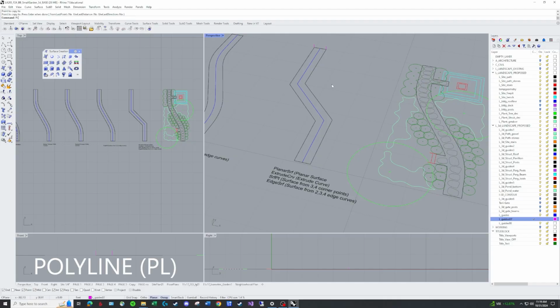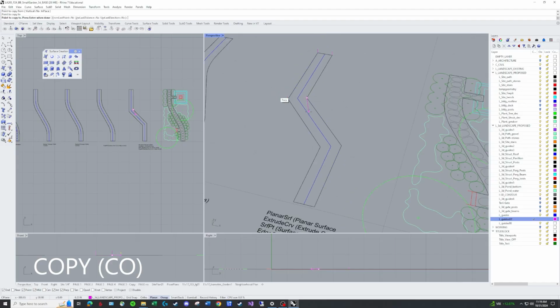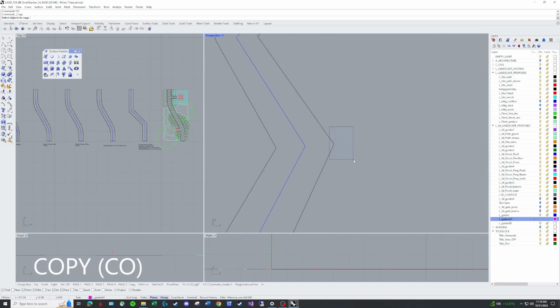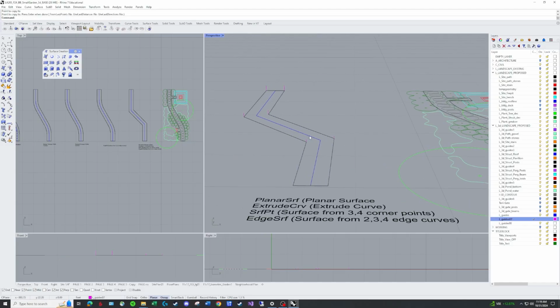So I'm going to use polyline again. Pick a point here, come down to the right, I just type in 1 first, and then hold ortho, left click, enter. And then I'm going to copy that from the endpoint to the endpoint. Do this one more time for 6 inches, 0.5, enter, and then ortho, left click, copy. Okay, so these are my little guidelines.